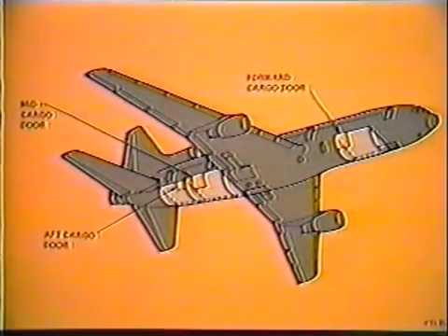All three cargo compartment access doors are on the right side of the aircraft. These doors are normally opened and closed electrically. If a cargo door actuator fails, the door may be manually cranked open or closed by use of a hand crank, stowed in the forward avionics compartment.